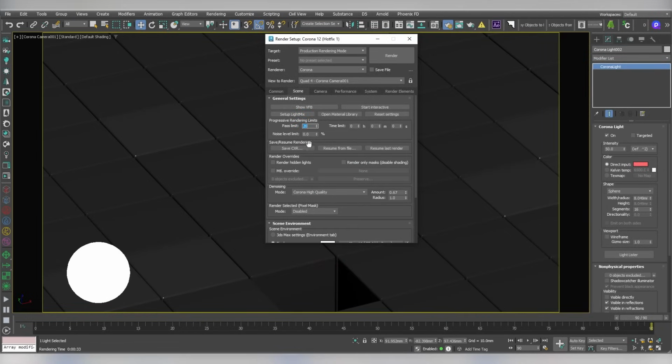One very important note, if you are rendering an animation, in render setup go to the performance settings. Under UHD cache, make sure to set the preset option to animation flicker free and the precision value to 2. When rendering an animation, the program renders each frame separately, so you might encounter flickering lights or strange light bursts in different frames. You need to be careful about this.